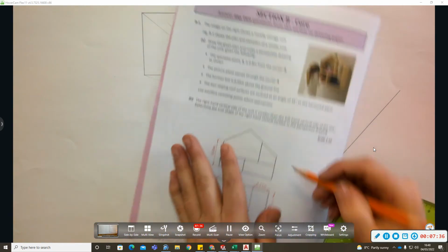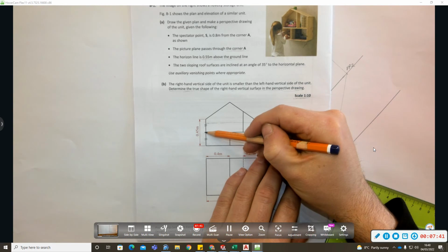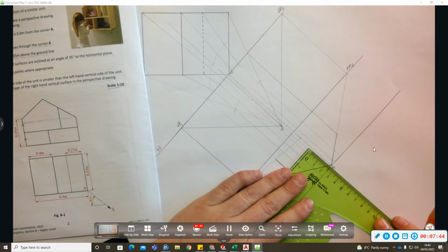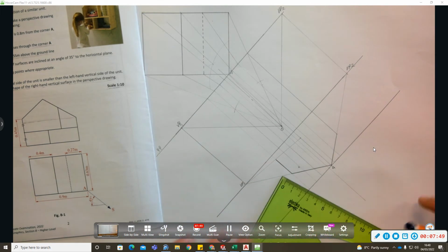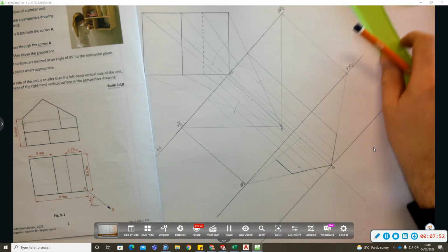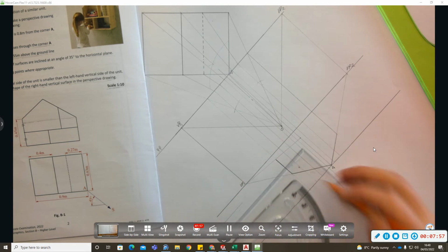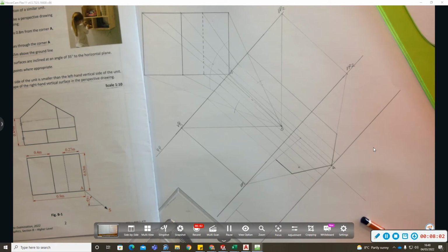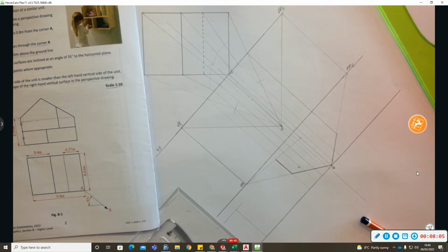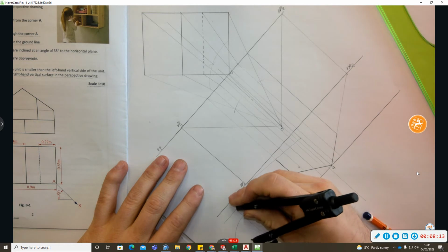Now, I don't know the height of that yet. It's lower than the one on the left. What I do know is these two dashes mean that they're equal. Now, some students will just get their set square and mark 22.5. No, don't do that, or you're going to lose marks. We are going to bisect a line that's 45 high. So I'm just drawing one out there, that's a height of 45. Or you could do a horizontal construction line and make it 45. We're just going to bisect the line. So I'll take my compass, set it more than halfway or to the length of the line.